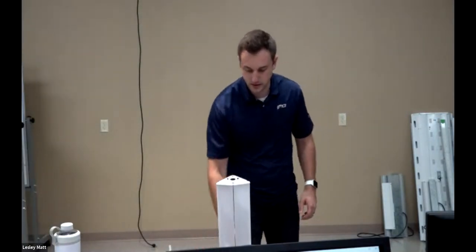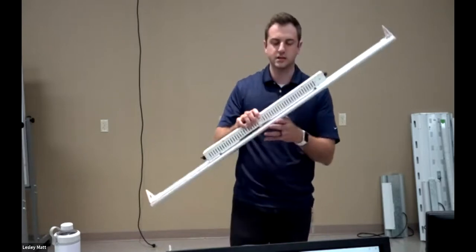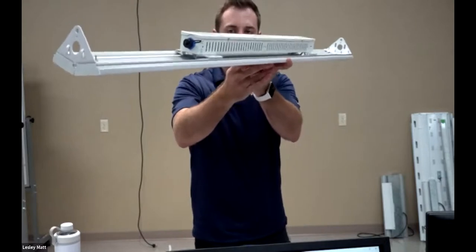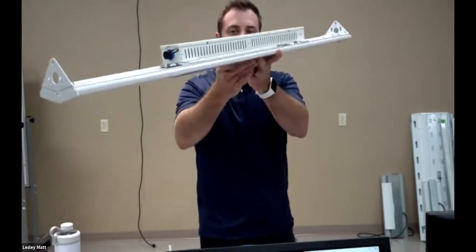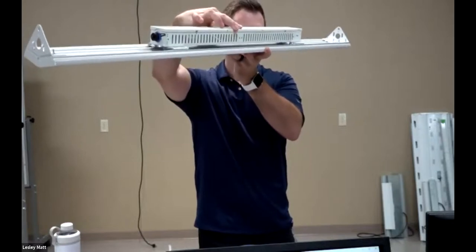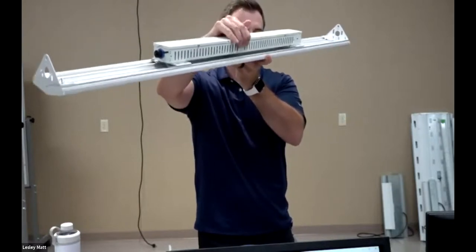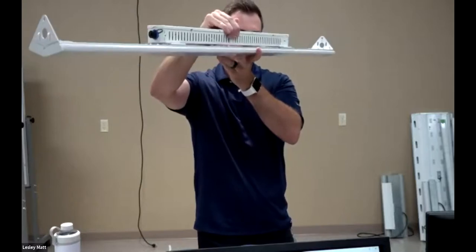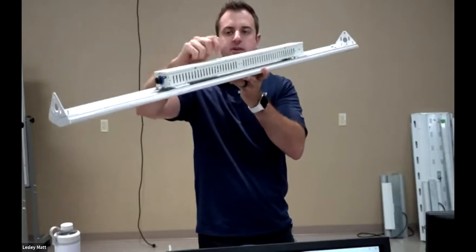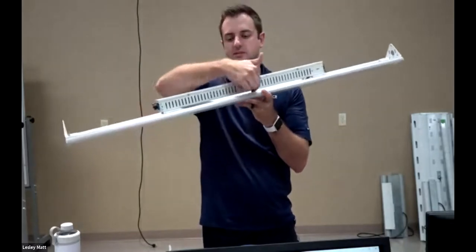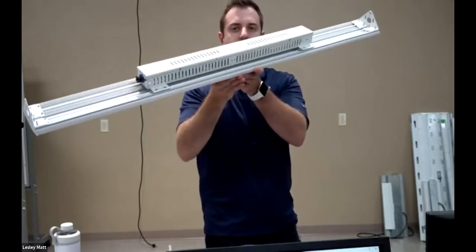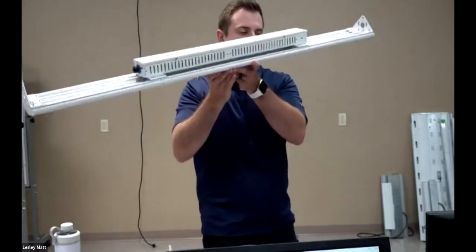Okay. Oh, and then for heat management, so we talked about this on the video, but here you go. You can see that we added a little gap, a pretty significant gap actually, between the driver. The driver sits up off of the unit. So that's going to be great for that heat application. We're not worried about heat at all on this guy and reliability. And that's down to both the driver, the TCP driver that's used in here, but as well as we just designed mechanically within the unit to limit heat transfer between the LEDs and that driver right there.